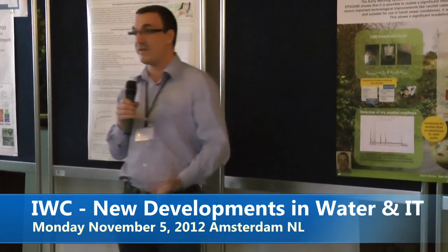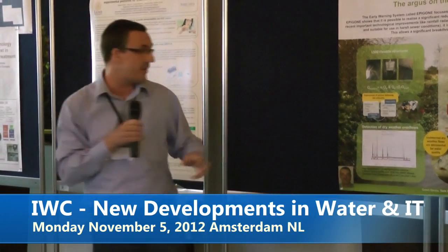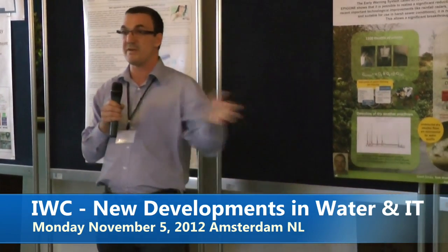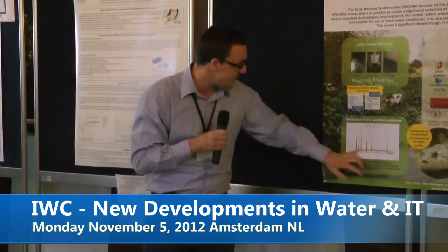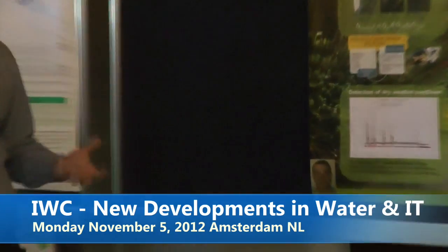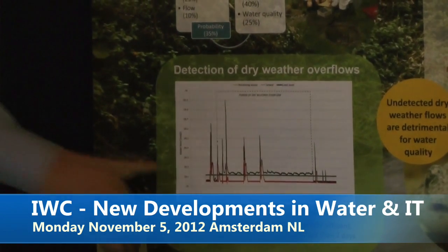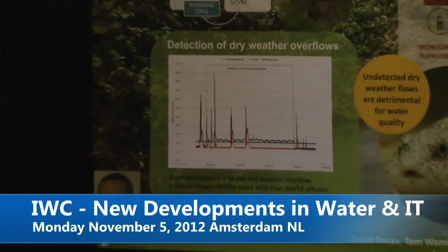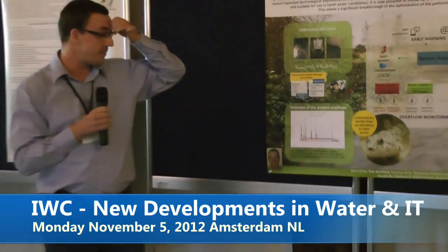So for this, we started measuring those devices. They have a simple QH relation. We measured upstream and downstream of the pipe and the flow through the pipe, and we also started measuring an upstream overflow, because these structures are combined sewer overflows. We saw that from a certain point on, we had a lot of overflow, also during dry weather flow, which of course cannot happen in our network.